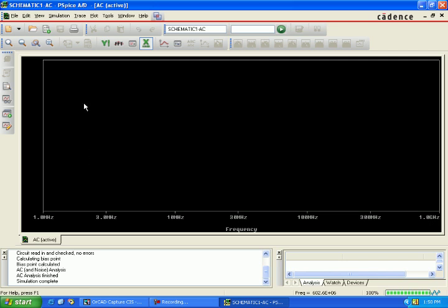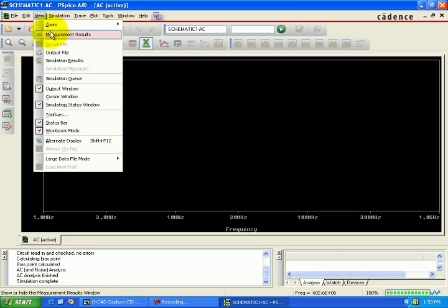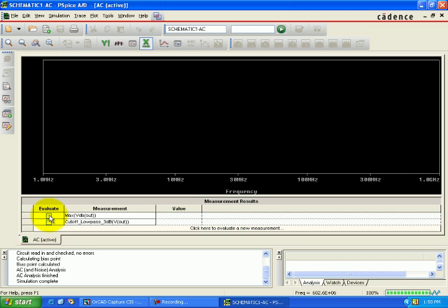Because we know that the values are not coming out appropriately as far as power dissipation is concerned, we have to increase the resistance value, so we change it to 5k.